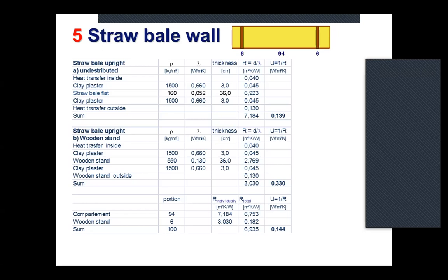It would be a 1 centimeter metal post through the whole wall. Of course, it wouldn't change the total U value that much, but it would cause a decrease of temperature, maybe by 14 or 13 degrees, exactly at the point of the post. At local, yeah. Yes, and then there could be growth of mold and additional things going on. So this is only one point, but you're right that for the total U value, it doesn't change too much.